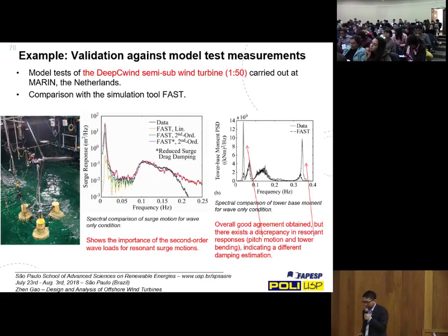These blades have to be designed so that they match the thrust force for the given wind speed at model scale. You cannot really geometrically downscale the rotor, because you get a relatively low Reynolds number and do not get satisfactory lift and drag coefficients.